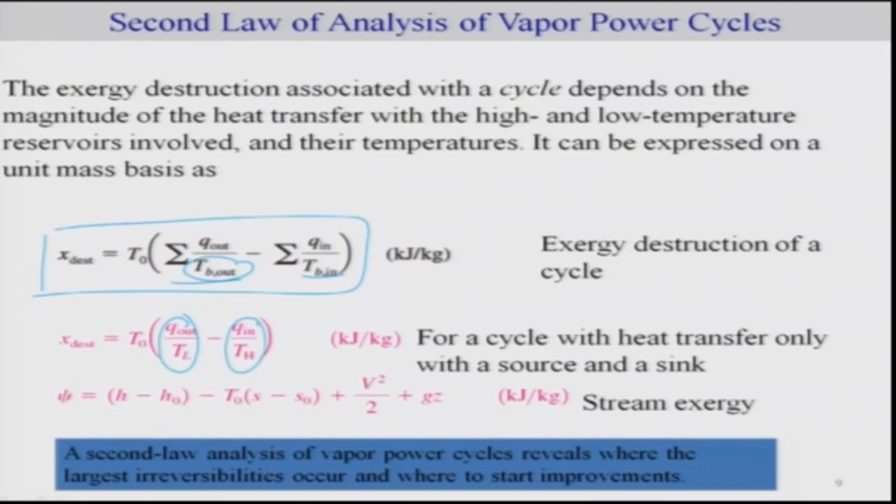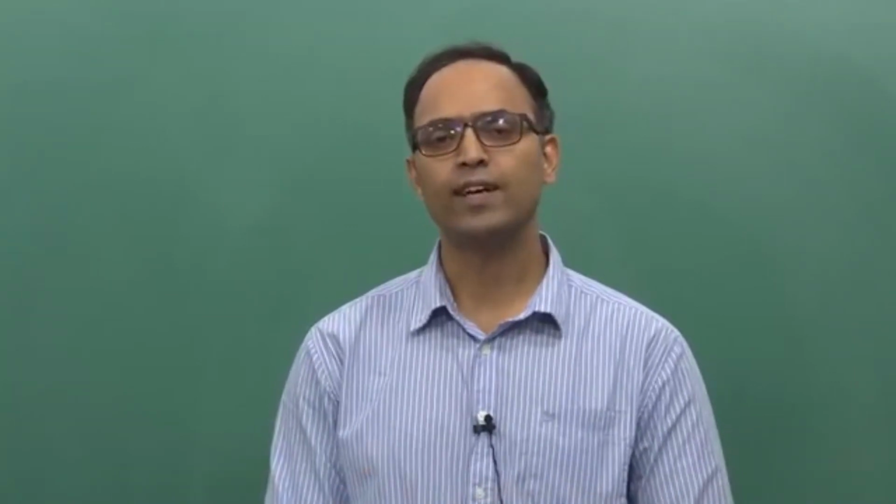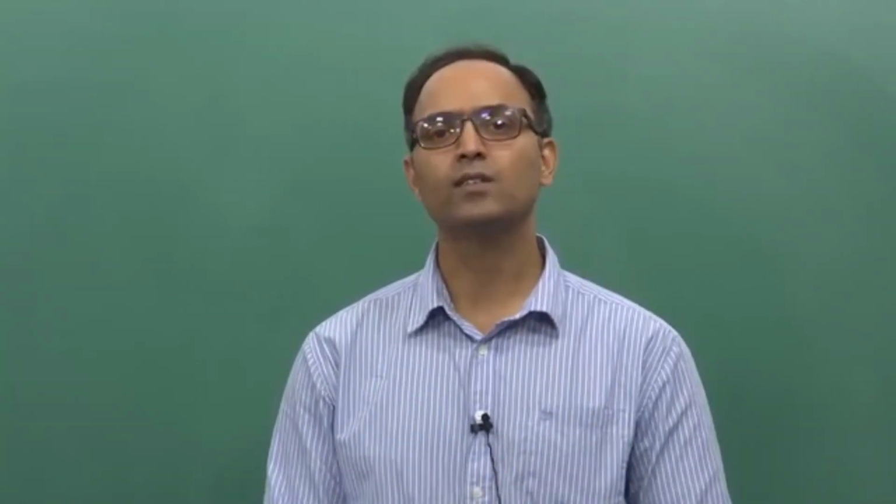Okay, so assuming this is a sink and this is your source, and this is, of course, the exergy which we can make use of. Now, one can analyze such a problem, but the idea behind using the second law is to find out the largest irreversibility, and that is where we can also find out how to improve our process for the problem at hand. By finding out the highest irreversibility, you possibly can come up with a new design which can minimize such irreversibility.